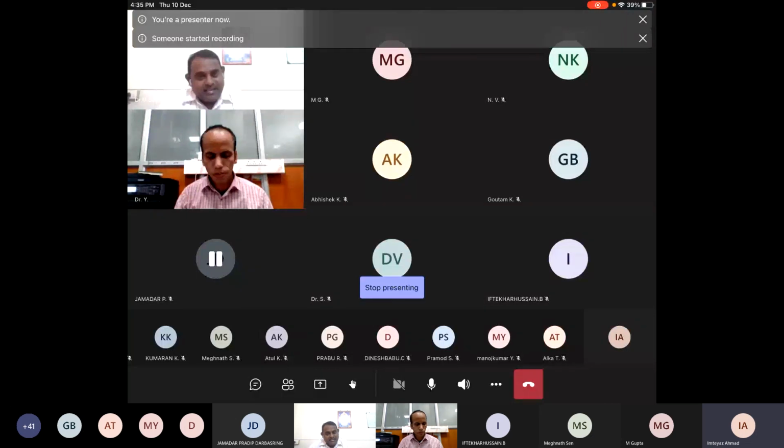Each layer will have its own hardness depending upon the material on that layer, and hardness is a very local property. Strength-wise, if you apply loading to open the layers, that will not be stronger. If you apply loading where the layers are elongated together, that will be stronger. But hardness will depend on the material itself.